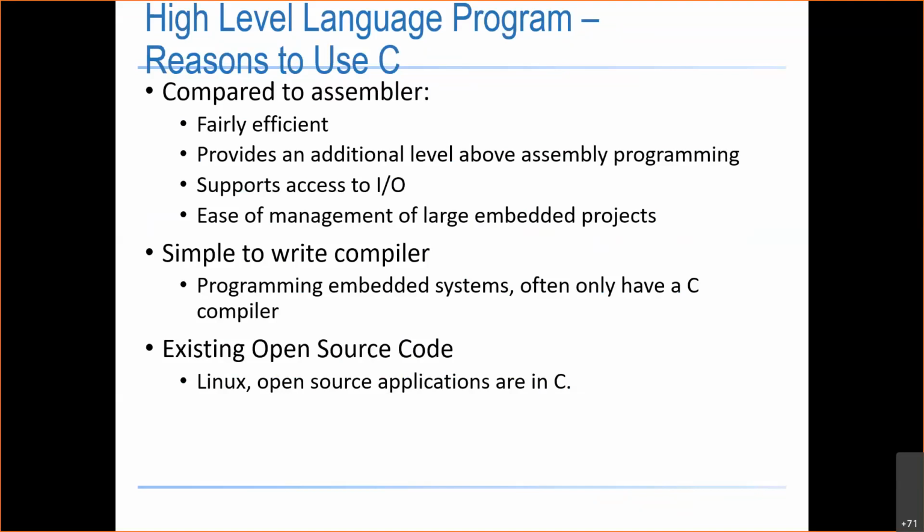This makes it very flexible for you to develop your application or your product. If you write your code in assembly, then it is only targeted to that chip. So if I write a code for ATmega32, which you have done maybe in last semester, and now I want to bring the code and run it on my Intel processor, the assembly code will not work, because the assembly code is targeting this processor only, this ISA only. But if you were to write the code in C, then with minimal changes, the code can run on different platforms. So that makes it very portable.